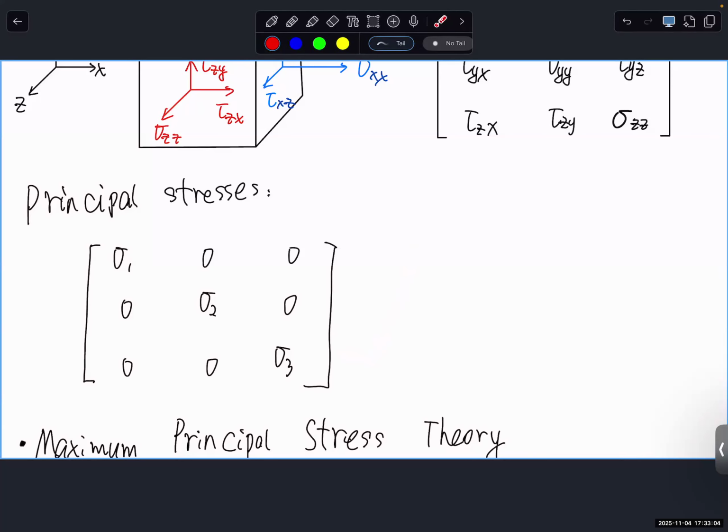So now, why do we need this? If any of you learned material science, you know. It's about how the material will break. As an engineer, I can only use examples. Glass and ceramic are brittle materials. They fail because of breaking the atomic bonds between atoms. And for the metals we normally use, let's say aluminum for aircraft, the structure fails because of the sliding of atoms in the microstructure.